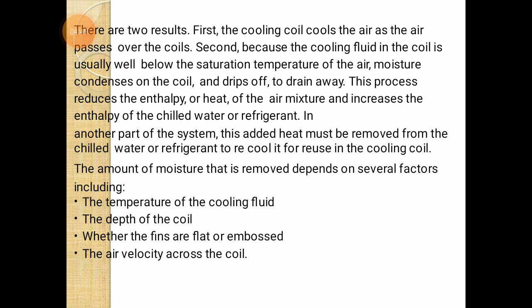So there are two results. The first, the cooling coil cools the air as the air passes over the coil. Second, because the cooling fluid in the coil is usually well below saturation temperature, moisture condenses on the coil and it drips off and it has to be drained away. This process reduces the enthalpy or heat of the air mixture and increases the enthalpy of chilled water or refrigerant.